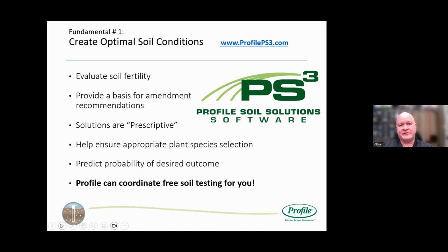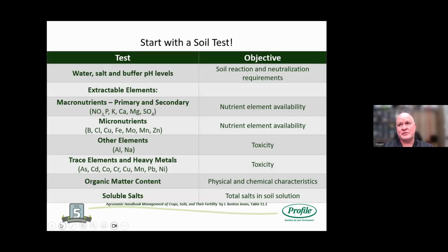This is a little bit like going to the doctor and saying, well, I don't feel well, and they just turn around and give you a prescription. Well, they don't know what's wrong with you. They usually order tests, and then based on those test results, they'll say, this is what we're prescribing. So when we're testing soil, we're testing for basically the buffering capacity and pH levels. pH level is critical in soil. It is probably the single biggest effector of whether or not you're going to have sustainable vegetation growing on your site. It's very easy to get plants to germinate and come up. Oftentimes, we get a month or 2 down the road and the plants don't look so well. So what often happens is people water more, then they realize that's not solving it, so they water less. That doesn't solve it.